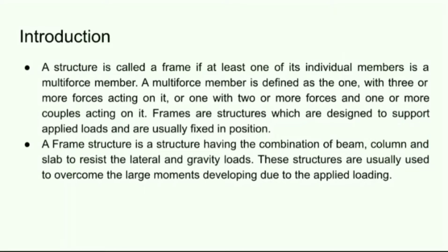Frames are structures which are designed to support applied loads and are usually fixed in position. An example of a frame is the RCC building that we usually observe in and around us. You can also define the frame as the combination of beam, column and slab used to resist the lateral and gravity loads. These structures are usually used to overcome the large moments developing due to the applied loads.